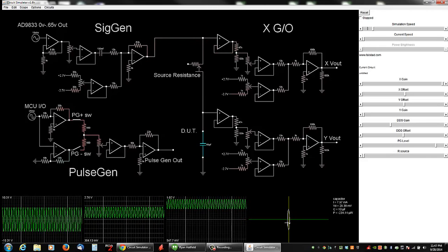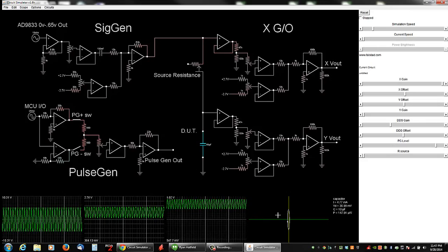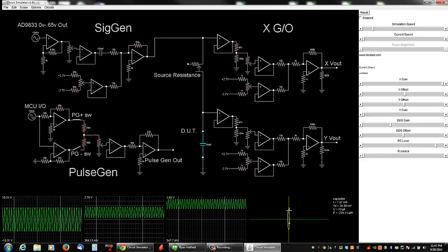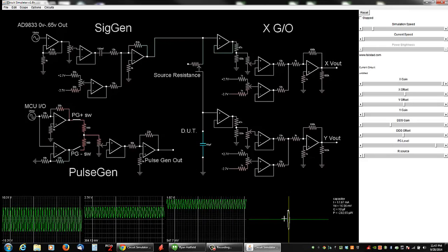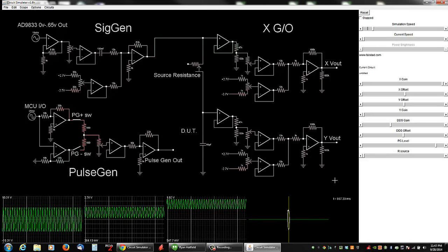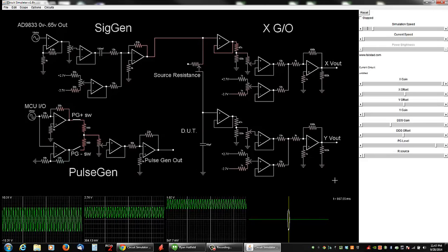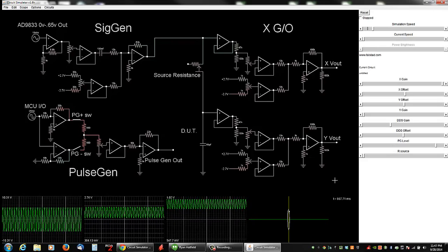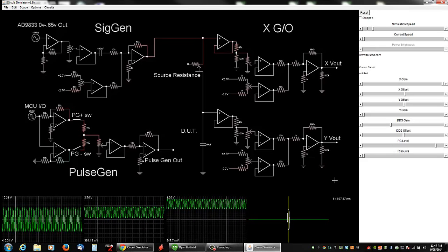Now at 10 kilohertz, it's even more of a short than an open. A short is a vertical line, and an open is a horizontal line. So you take any one of those, any combination of those, you get a circle with a tail on it. Kind of looks like a golf club. That would be a diode in